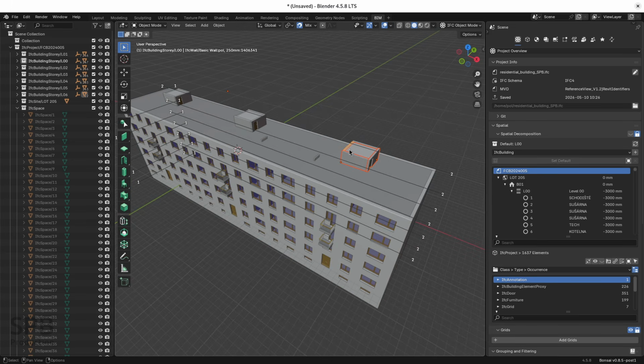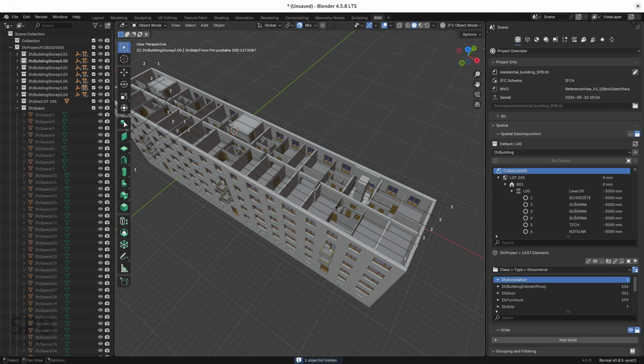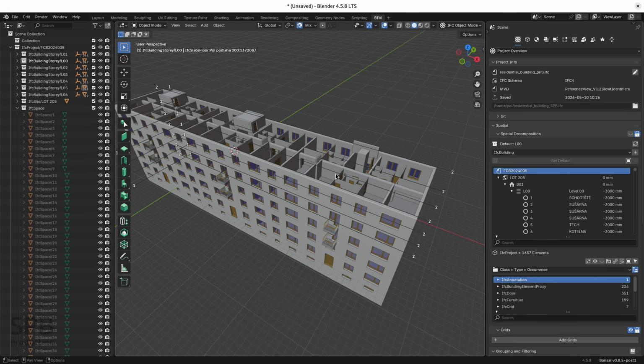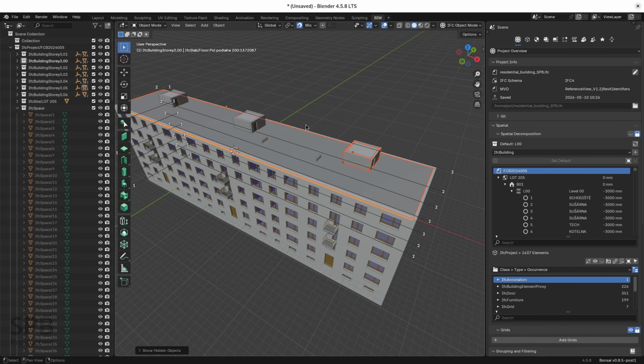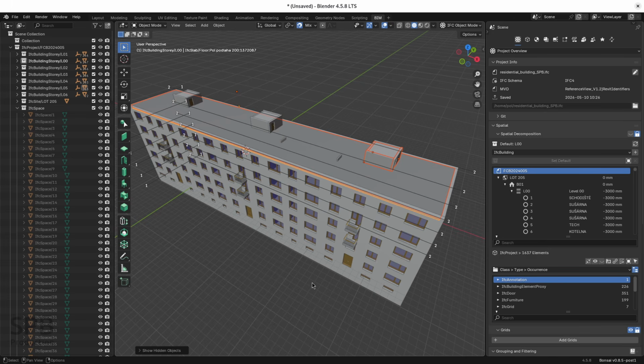And of course sometimes I want to hide objects, so if I wanted to hide these I would just press H as in hide. So this hides these objects, so I could hide this slab and hide this slab again, so I can see inside of my floor. And to unhide the hidden objects I will press Alt H. Alt H reverses the hide, and so every hidden object is unhidden with Alt H. So you have to be a bit careful about that. But at least you have a certainty that all of the objects are unhidden.